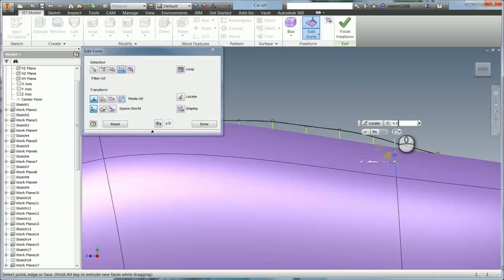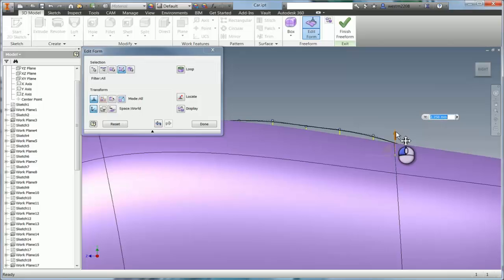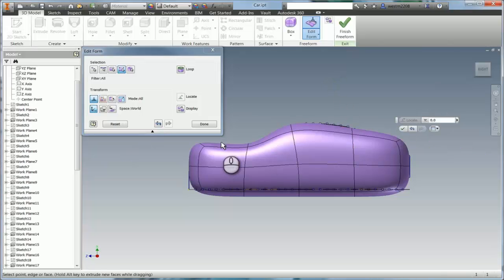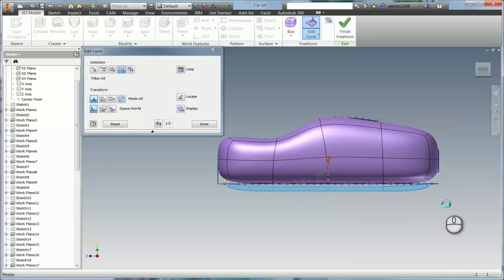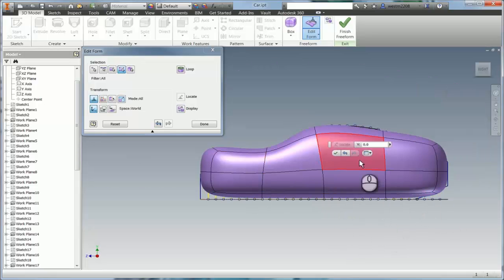If I do an edge, it works exactly the same as a face, so you can see there, just adding an edge. So with the rotate and the edge translation, you can see you can start to really get the shape pretty quickly. So I'm just going to move all of these up to just line them up with our sketch, so there you go. You can see how even with just these 4 faces we can get almost the right shape.